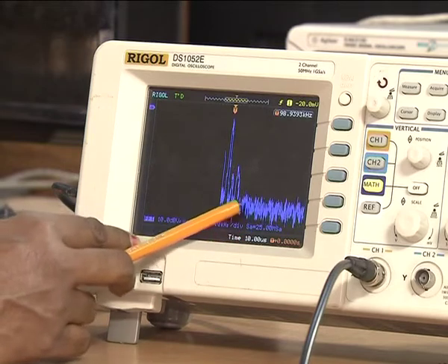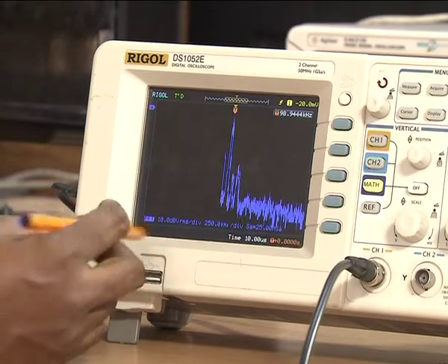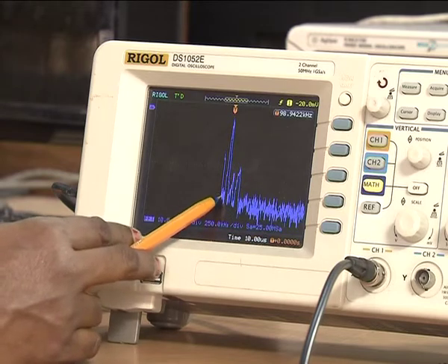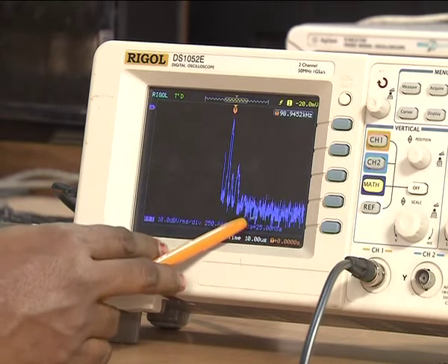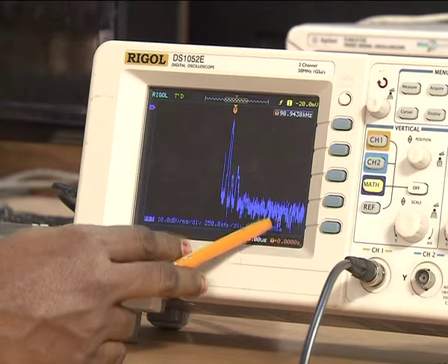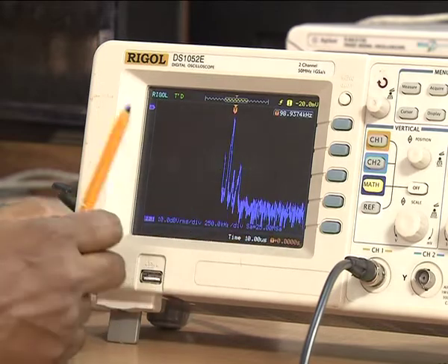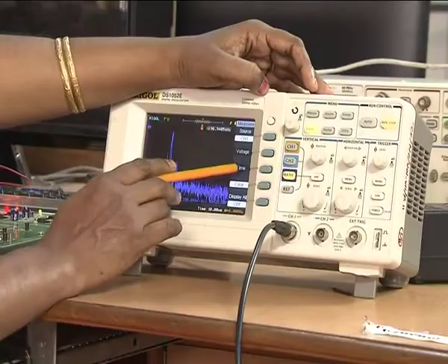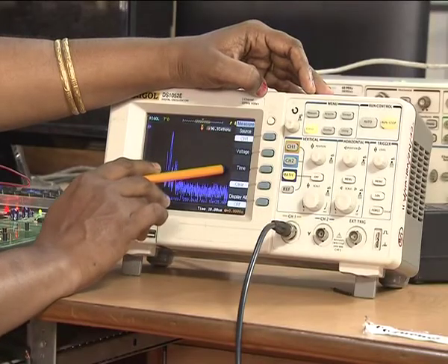This is the frequency of the FM modulated signal. Using this, now we will be measuring what is the beta for this frequency of the FM modulated signal. To measure the beta, we are going to use the cursors, which will say what is del F. In that, we can measure either voltage or time.